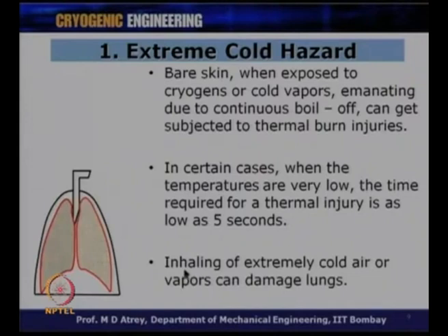Also, inhaling extremely cold air or vapors can damage the lungs. If you are in an atmosphere with a lot of liquid nitrogen in the air, near the plant for example, where liquefied air, liquefied nitrogen or any other liquid gases or their boil off is in the air, and you inhale those cold boil off vapors, they are not at ambient temperature, they are still cold, and it can damage the lungs.